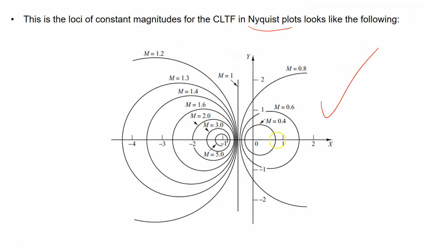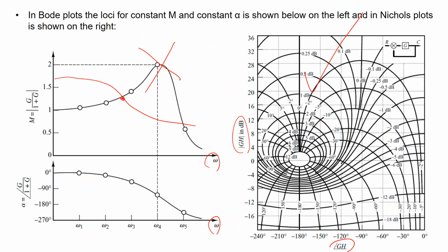And we don't do it here. Again, why don't we do it here? One more time, because in either of these two curves, either this top one or the Nyquist, if I change my gain from one number to the other, so if this is k of 1, if I make k 3, it just shifts up. And the same here, if in the Nyquist plot it looks like this, for example, if I change it, so this is for k of 1, if I change it to k of 4, again, it's going to be simply shifted up.